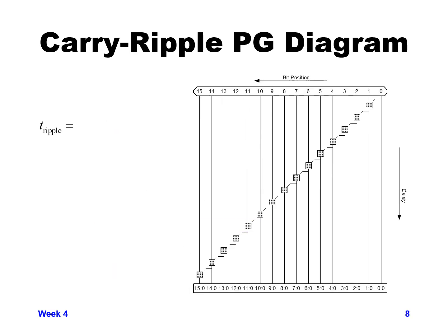So we've been talking about a carry ripple adder for the most part. So let's see how the actual delay could be calculated going through a 16-bit, 15 colon 0, carry ripple adder using this type of propagate generate functionality that we've been talking about in the previous few slides.